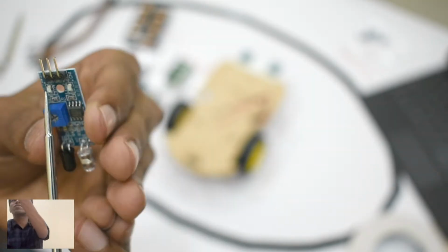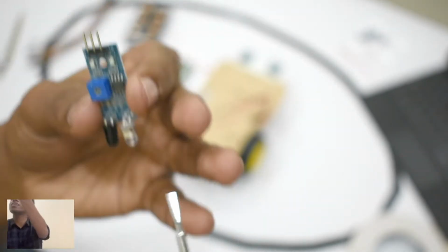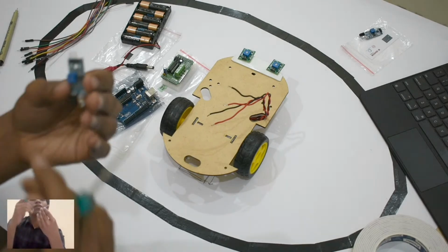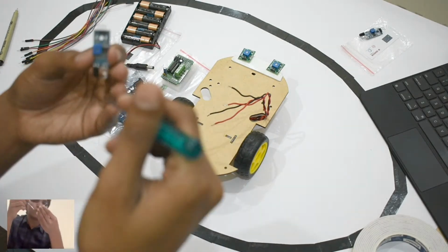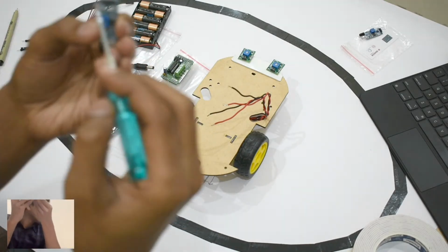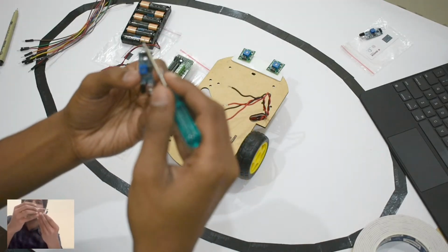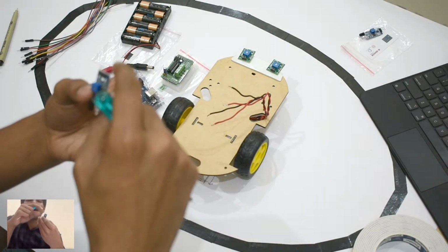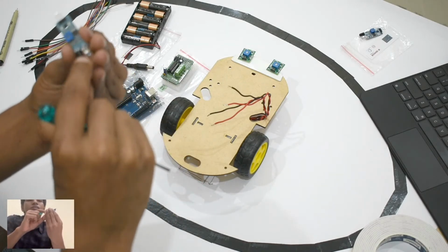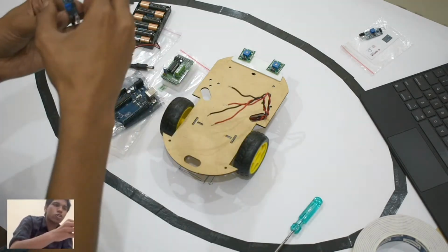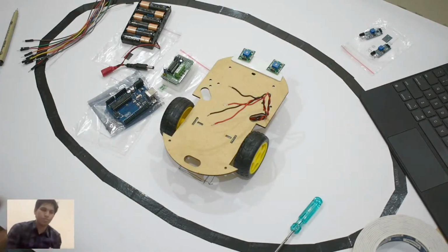So pins are always numbered, pins are always labeled. Any circuit that you get, their circuits are going to have a serial number that you can search on the internet and find out their diagrams, which pins are what. Okay, but then it's written here as well. So the first pin is where I need to supply power. The second pin is the ground pin, and the third pin here is where I get the data of the amount of light received by my photodiode. So pins are going to be crucial. You have to remember which pins are what.